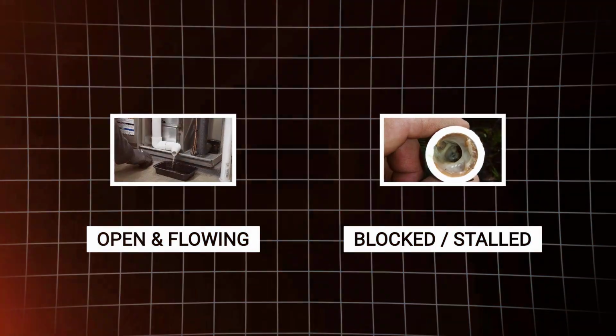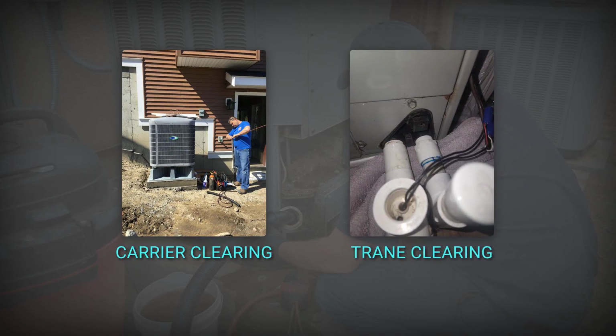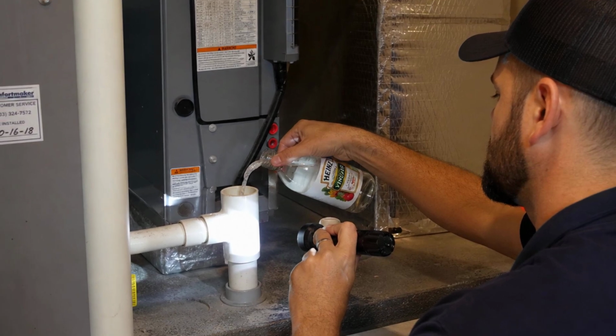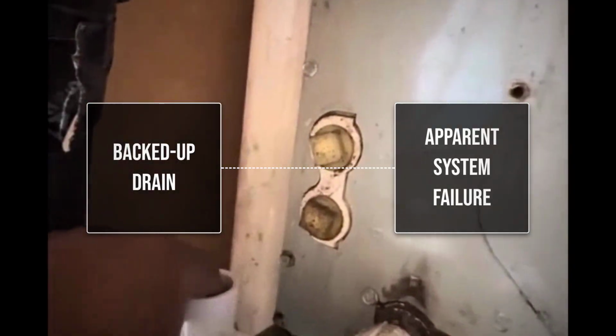This gives you the main diagnostic split for the video. Once backup, overflow, or repeated shutdown appears, follow the clog procedure. Carrier and Trane both describe physical clearing methods for that condition. Reserve vinegar for approved preventive maintenance in a freely draining line, and a backed up drain can trigger a symptom that looks much more expensive than a clogged pipe.